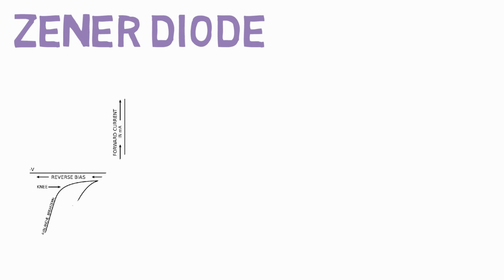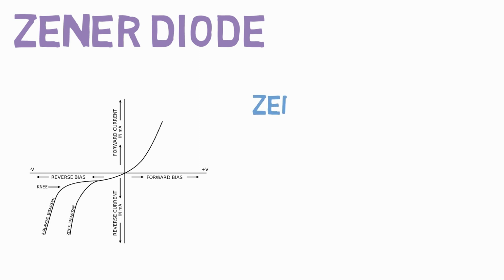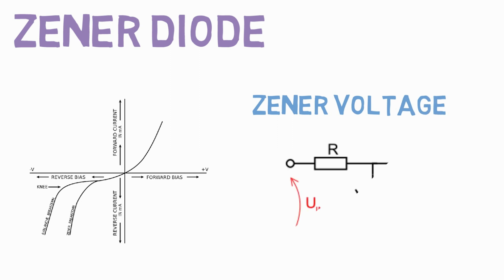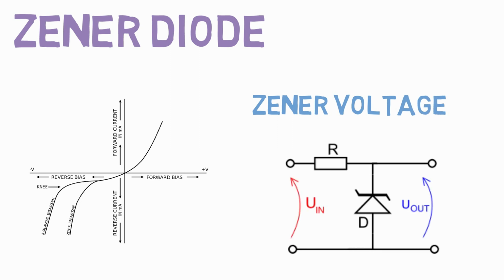A Zener diode is a diode which functions as follows. When the Zener diode is reverse biased, which is to say the cathode is more positive than the anode, it breaks down at a voltage we call the Zener voltage. This does not destroy the diode, but provides a voltage we can use for reference or regulation purposes. While this Zener diode regulator circuit has the application, the quiescent current of such a device is quite high, usually heading into the tens of milliamps range.